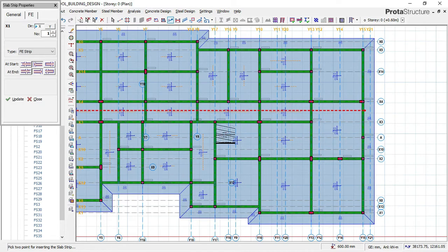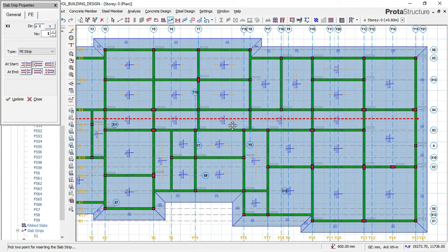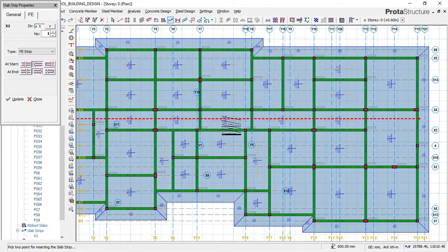I'm not going to cut every panel because the whole idea is just to get the value of my slab reinforcement spacing and also the size of the reinforcement. Then once we get these two values, we will use the customized Stonebridge, the customized Prota structural detailing template, which is the Stonebridge template, to perform this Raft Foundation design, which I also do in part 3 on the Raft Foundation detailing.